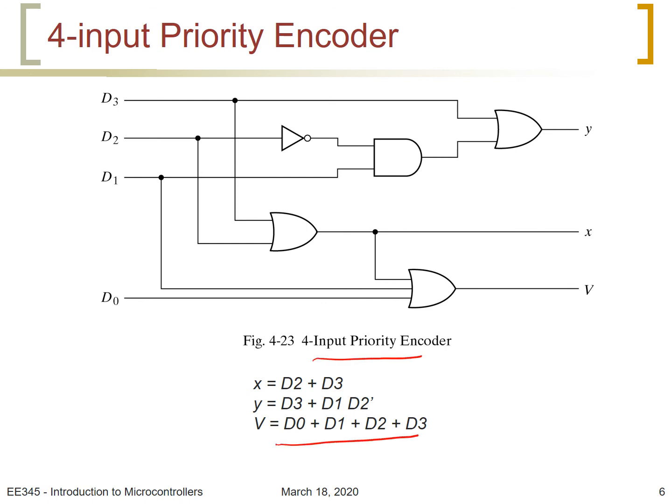Of course, V, if we look back at the truth table that we developed at the beginning, V will be 1 when any of the inputs D0 or D1 or D2 or D3 is 1. Therefore, all it takes is just an OR gate with all these variables as inputs, as we can see here. And this concludes our discussion of the priority encoder.